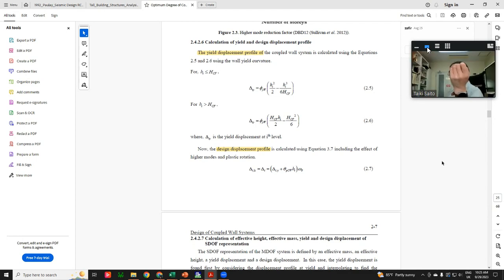Sensei, can I have one question? We can see that for El Centro and Kobe, the difference is too large, right, Sensei? Can we compare the displacement-based design method with the time history, not only for one earthquake, but the mean earthquake? So it's more valid, because if we compare to a small earthquake and a big earthquake, maybe the result in between is good for El Centro, but it doesn't match with Kobe.